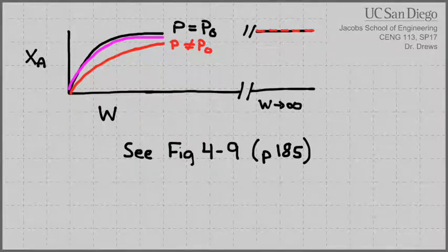For each one, there's a W, or a volume. It doesn't really matter which one. And then it shows 2 curves on there, one with pressure effects and one without pressure effects. It goes through things like conversion and reaction rate and concentration, so that you can see what's happening to each one of those terms when you introduce a pressure effect. We're only going to plot the one because we're already 25 minutes into this example, and we still need to get to energy balances.